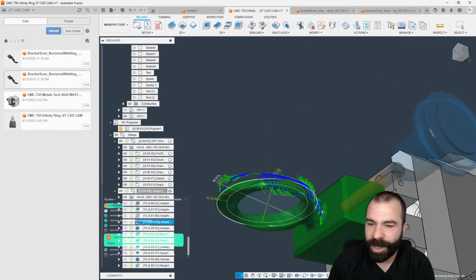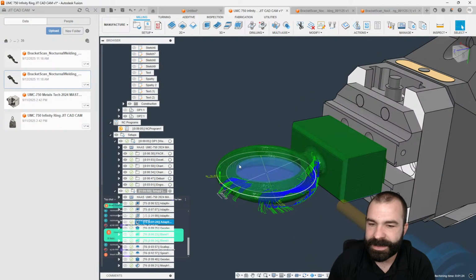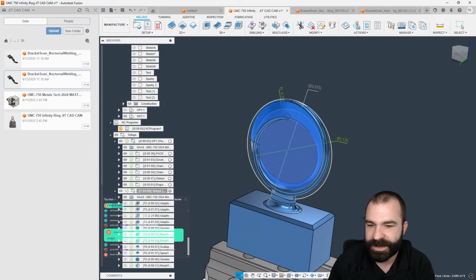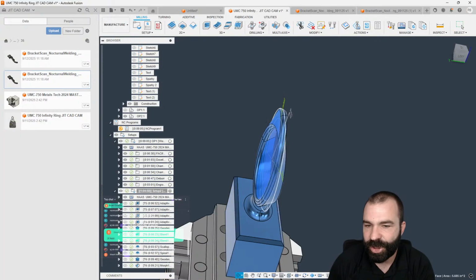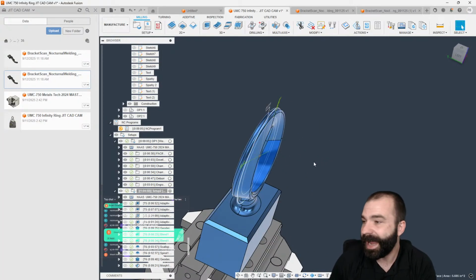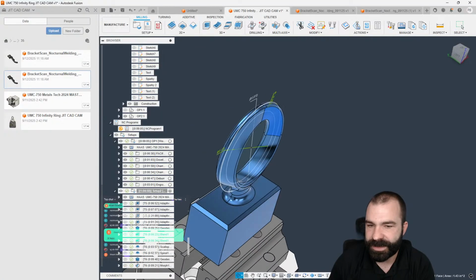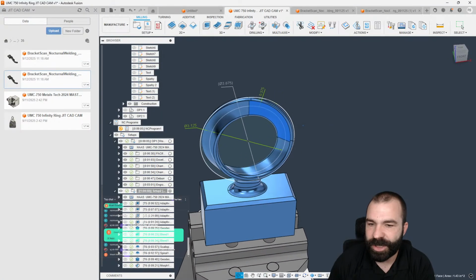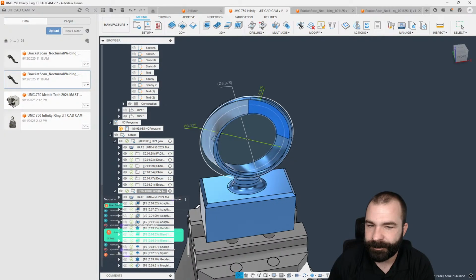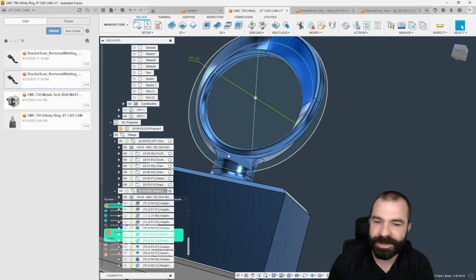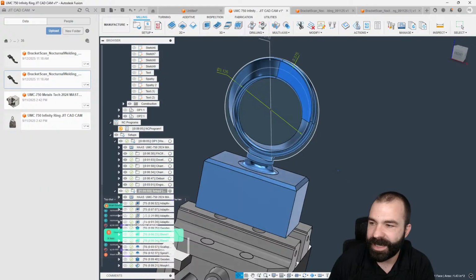But based on that type of information, if you're really concentrating and really trying to machine and surface something like this, my question always goes back to, what is the end goal of the surfacing you're doing, right? So again, if I had a 5-axis machine, we could look at even swarfing some of these surfaces, right? So keep in mind though, with our swarf, we've got to be aware of where we start and where we finish as well. At some point, we do need to flip-flop that profile. We're dealing with this knuckle down here at the bottom that's holding on, things of that nature, right?